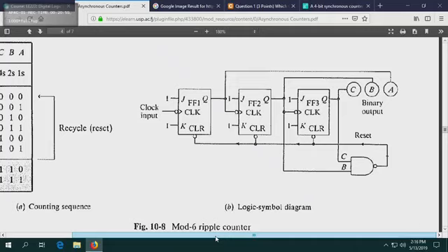Okay, now, asynchronous counters, another name is ripple counters, they only go in proper sequence. So they go 0, 1, 2, 3, 4, 5, 6, 7, 8, 9, 10. So if you're using 2 flip-flops, what is the maximum count? Maximum count will be 0 till 3, right?